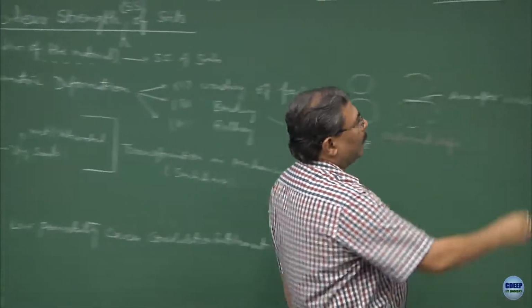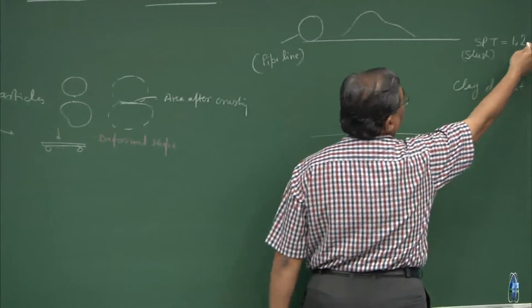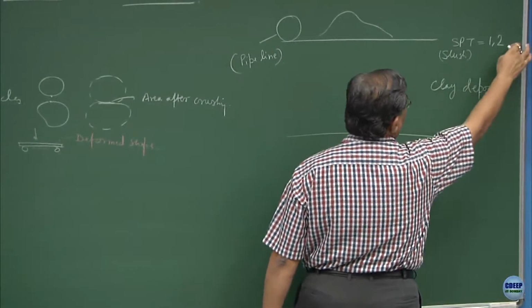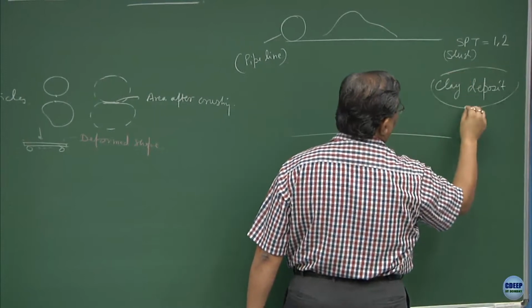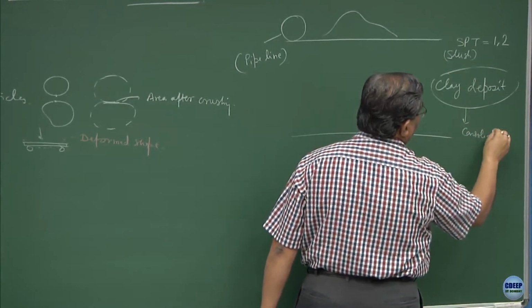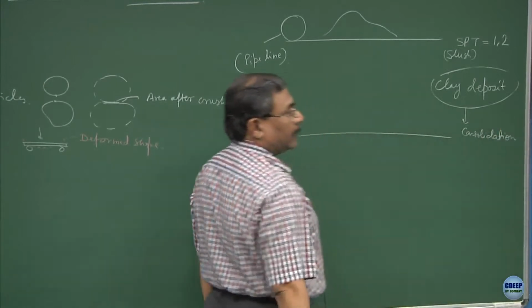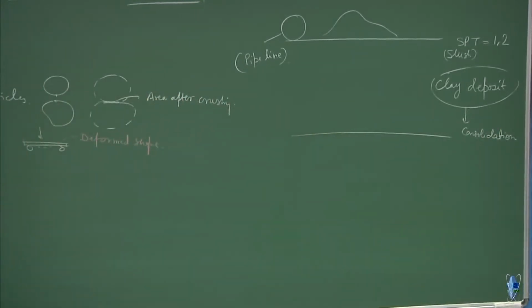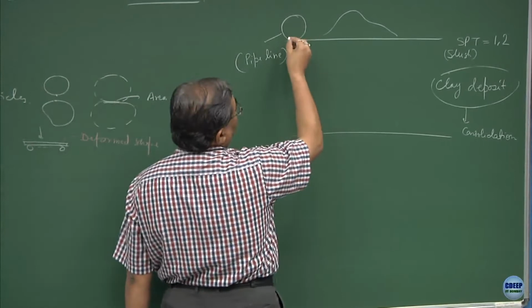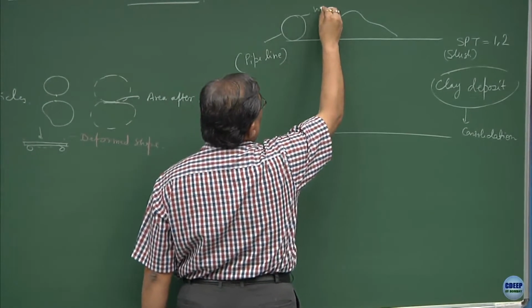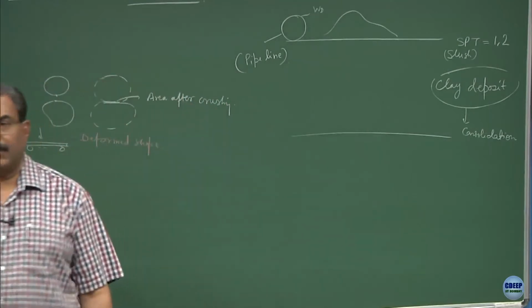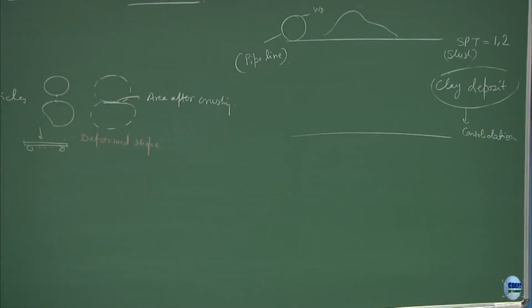Now, the question is, if you cannot stand on the deposit because of this poor strength, this again is the shear strength of the system corresponding to the clay deposit, which is liable to consolidation because of the external loading, correct. 3 clauses I have added. Initially, to start with, the pipeline has its own self weight or dead weight. These are kilometers long pipelines, 2.5 meter diameter pipelines carrying either your fiber optic cables, utilities, data connectivity, whatever, crude oil, any type of supply,